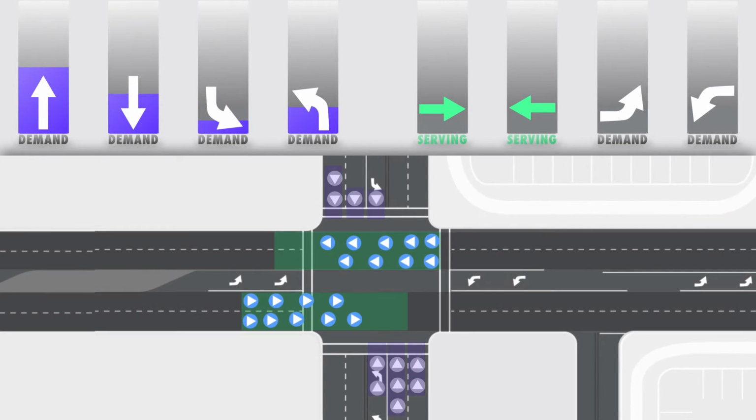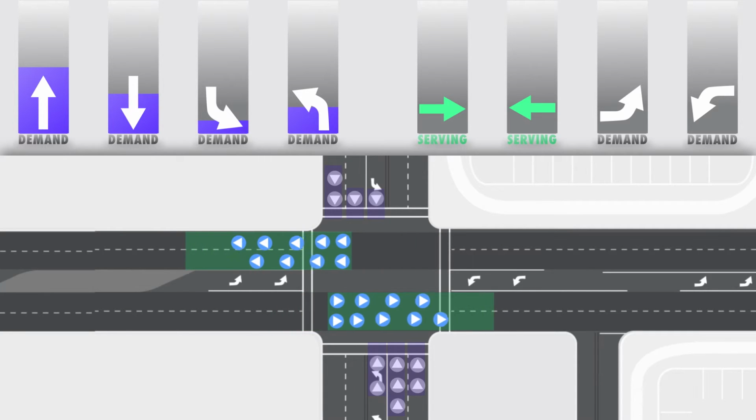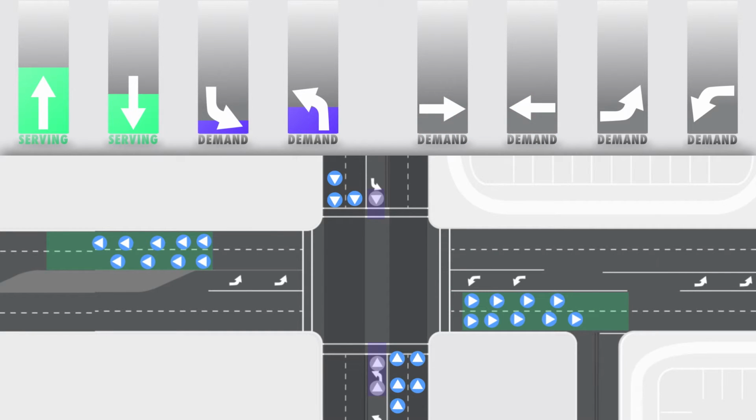Green time allocation is the process of administering the appropriate amount of green time to each occupied phase, while allowing InSync to skip empty phases as well as serve a phase multiple times within the same period when allowed. As soon as the tunnel is through, InSync knows that it must be able to serve all phases at least once before the tunnel is served again. If some of the phases are empty, like the east and westbound lefts, InSync will reallocate the green time normally needed at that phase to another phase with a higher demand, or to the reservice of a particular phase if needed. Let's watch as InSync begins to serve the demand at this intersection.